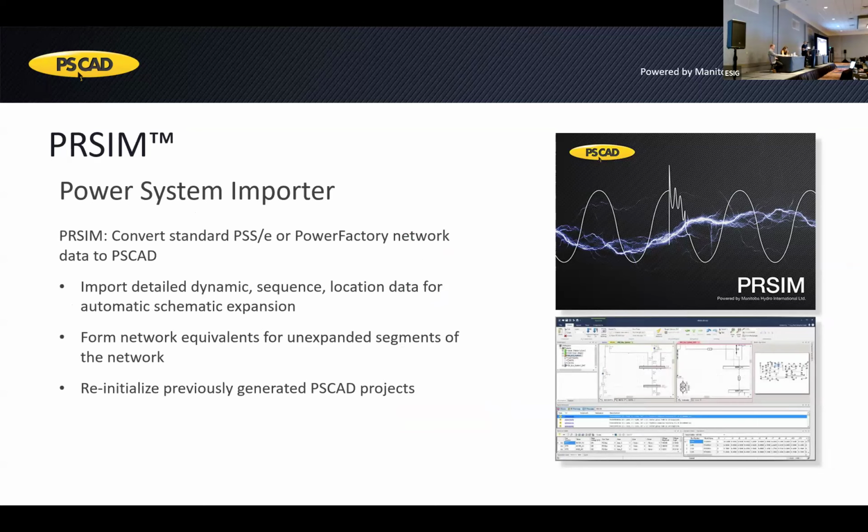With PSSE, we can import the raw data, the dynamic data, the sequence data, and the location data. The tool allows you to form network equivalents for unexpanded segments of the network, and you're able to reinitialize any type of new power flow you would like to investigate.